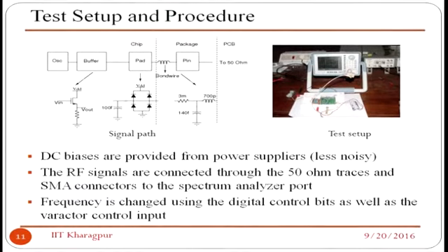So it is 3 milliohm resistance, then 700 picohenry is the inductance, and 140 femtofarad is the capacitance. So this is the bond wire parasitic value, and that goes to the pin, and that pin then goes to 50 ohm impedance. That means the PCB line of 50 ohm. So clear now?